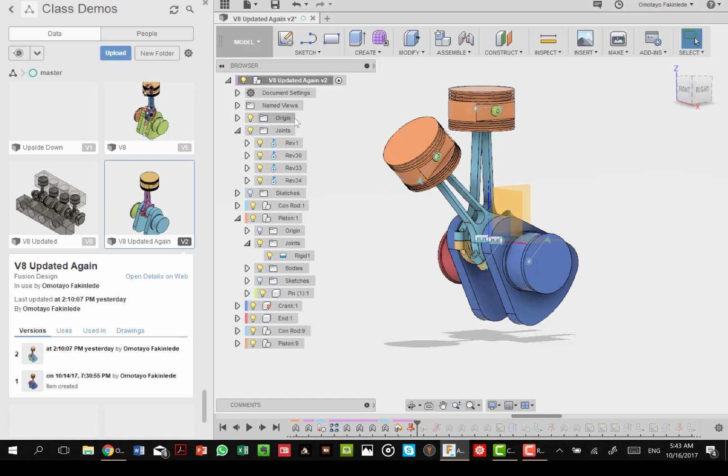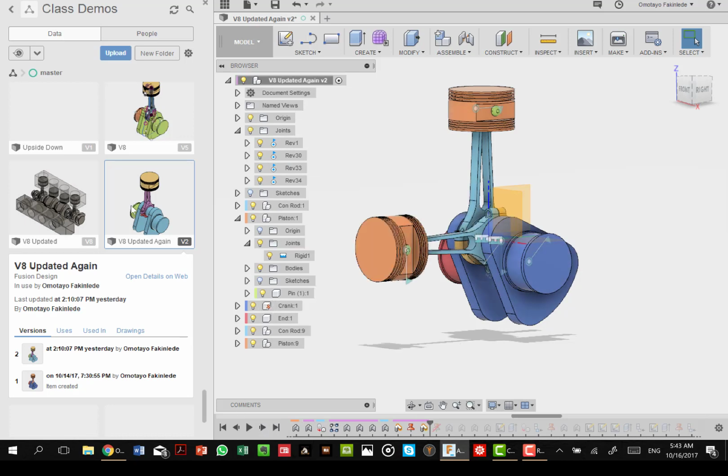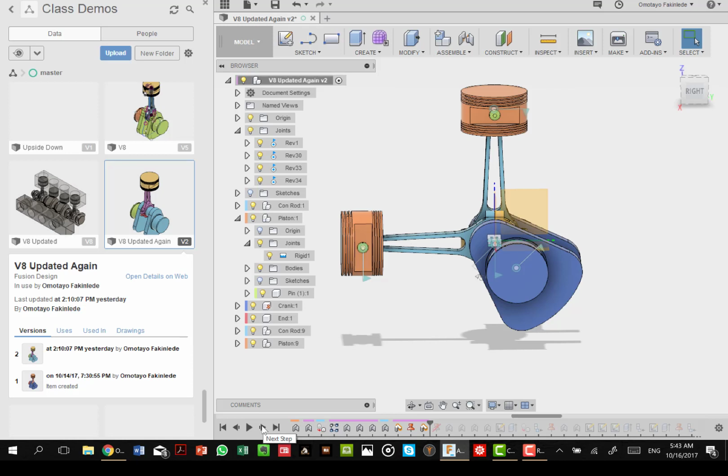and then once we have pinned down the crank, we can now request that there is an extra motion. The crank is grounded here, so we want now to make an extra displacement of 45 degrees. So we have these two pistons that are now oriented to each other at 45 degrees. At this point, we can go back now and unground that crank so that we can now complete the fixing of the necessary joints in the other connecting rod and piston before we begin the replication process.